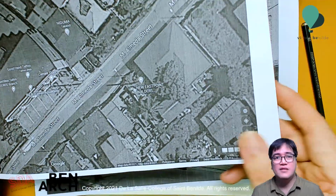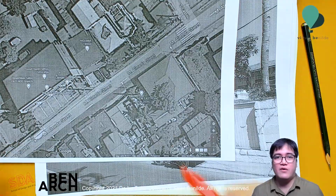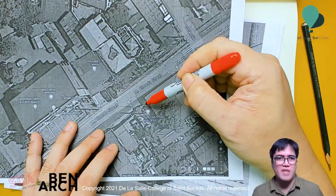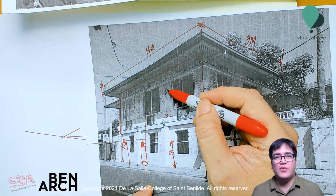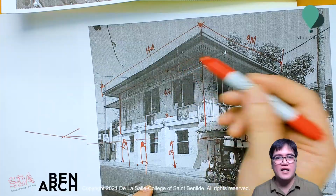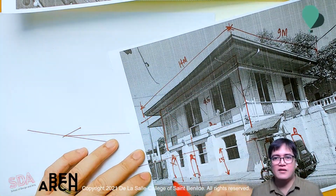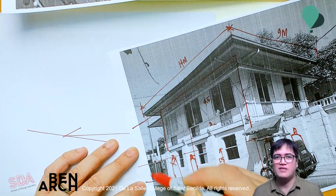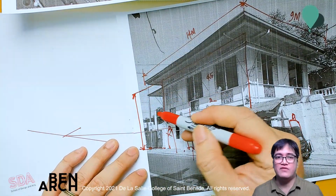Number 1, establish parameters, or in this case, the framework or overall proportions first. This includes the facade width, measured in Google Maps, floor level, and overall height. It is important to set the parameters or framework first so you can lock in the elevation boundaries. So check. Number 2, once you have established the facade width, you can now come up with a more accurate estimate of the building heights by proportioning through referencing available photos of the structure.